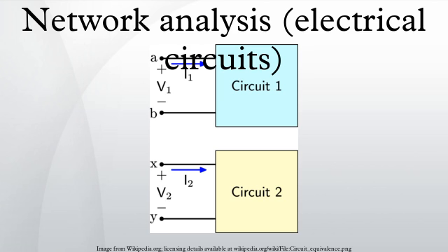Perhaps the easiest practical method is to calculate the network open circuit voltage and short circuit current and plot these on the transfer function of the nonlinear device. The straight line joining these two points is the transfer function of the network. In reality, the designer of the circuit would proceed in the reverse direction to that described. Starting from a plot provided in the manufacturer's data sheet for the nonlinear device, the designer would choose the desired operating point and then calculate the linear component values required to achieve it.